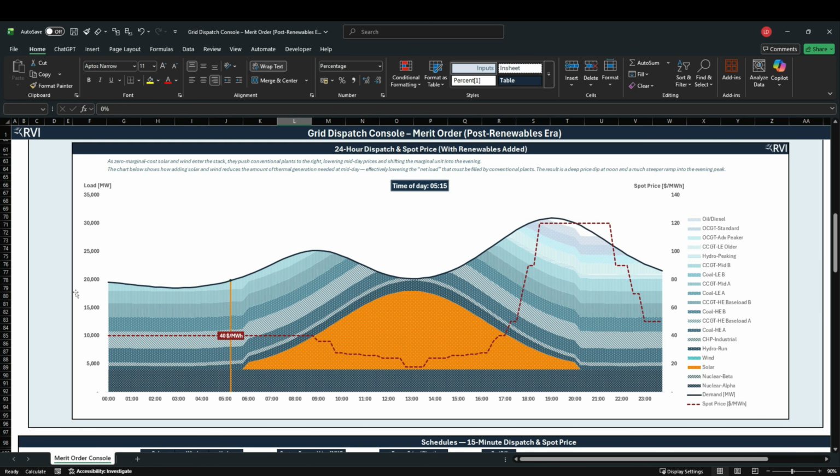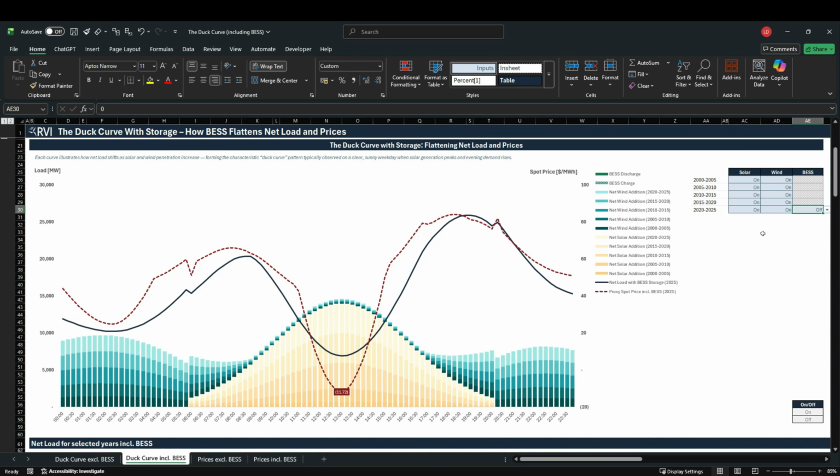In short, the system exchanged fuel cost for variability: lower midday energy costs, but greater evening scarcity and price volatility, especially after retiring 9 gigawatts of firm capacity without adding flexible resources. During the strongest solar and wind hours in certain energy systems, prices can approach 0 or briefly even turn negative, as must-take energy such as nuclear may exceed net load, and just a few hours later, meeting the peak demand can be tight. The missing piece here is flexibility.